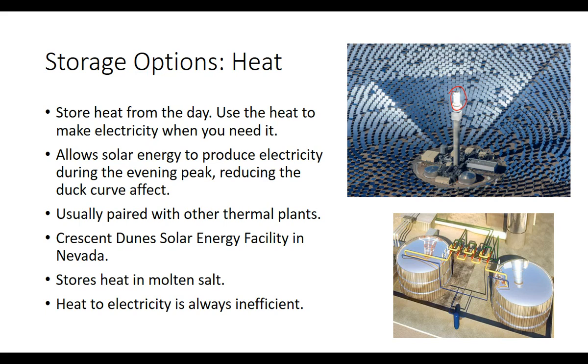Even when the sun goes down, this plant could continue to function because, if you see these metal, shiny looking tanks here, those are full of superheated molten salt, and so they're storing that thermal energy to be used later. Even when the sun goes down, they start using the thermal energy in those tanks to produce electricity as well. So this power plant could continue to run into 7 o'clock, 8 o'clock at night to round off that duck curve. And that would be very helpful.